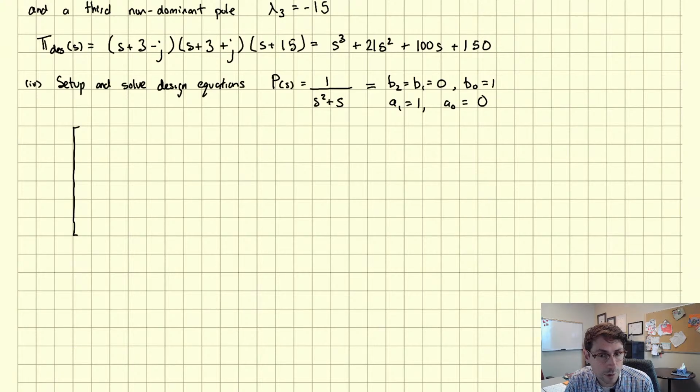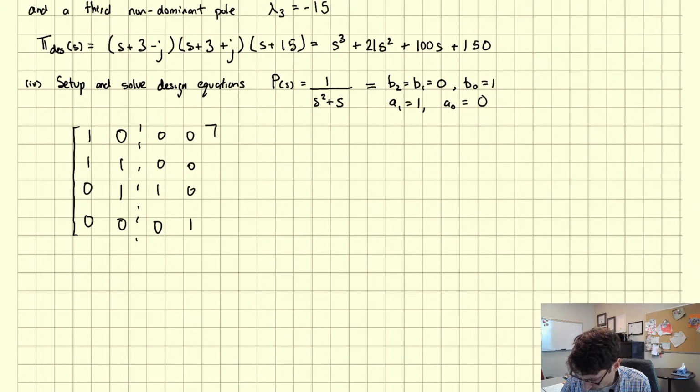Okay. So the first column just comes from the denominator. So we have 1, A1, A0, pad with zeros. Shift down. 1, that's this one here. A1, A0. Third column comes from the numerator. So in this case, B2 and B1 are 0, and then B0 is 1. So we get 0, 0, 1, pad with zeros, shift. Controller gains.